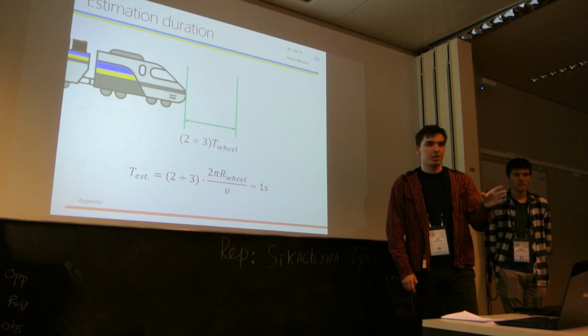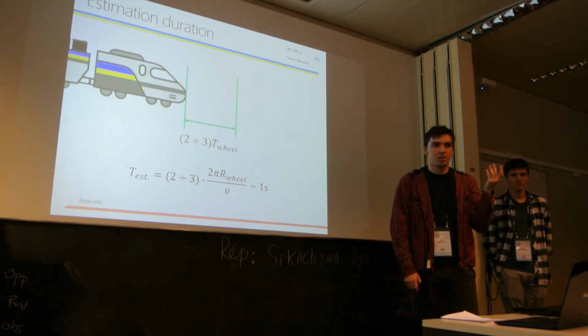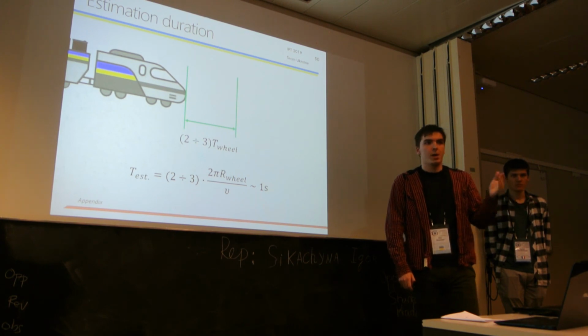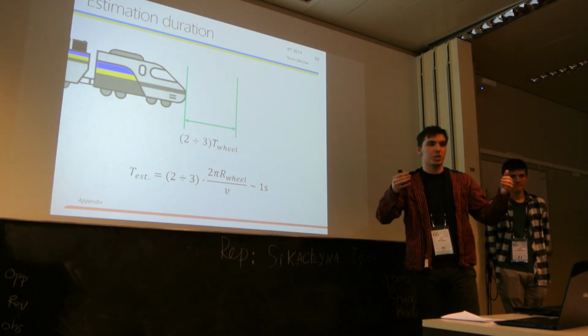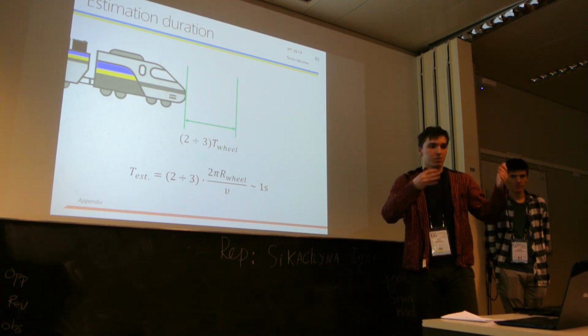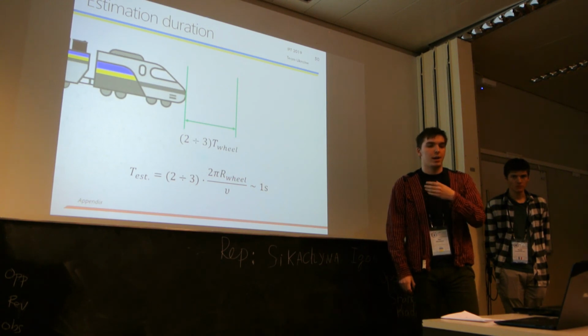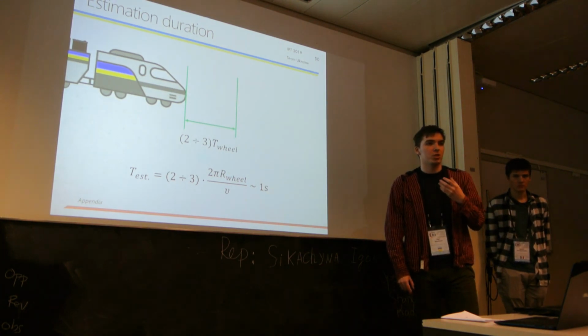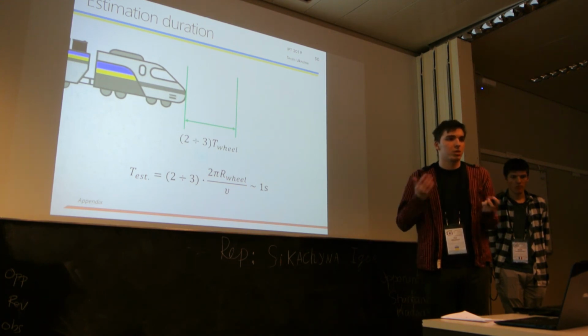We studied the train in about one season, so the temperature was more or less in the same range. But indeed, the rails change their attenuation coefficient and their length based on the temperature. But the change is not that significant compared to other problems for the distance estimation.